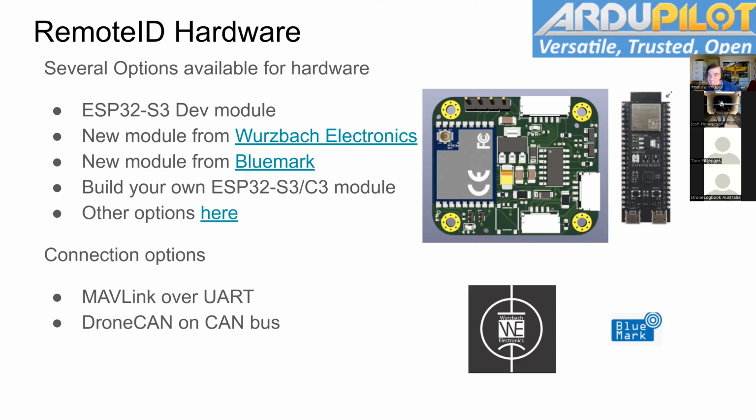Well, that leads into my other question, which may have already been asked. Due to the companion computer, if I'm out of TLM ports, can I plug in the ESP32 module as a USB device and forward the MAVLink over MAVProxy somehow? Yes, you could indeed. Does it have to be plugged in directly to TLM? No, you could indeed do that.